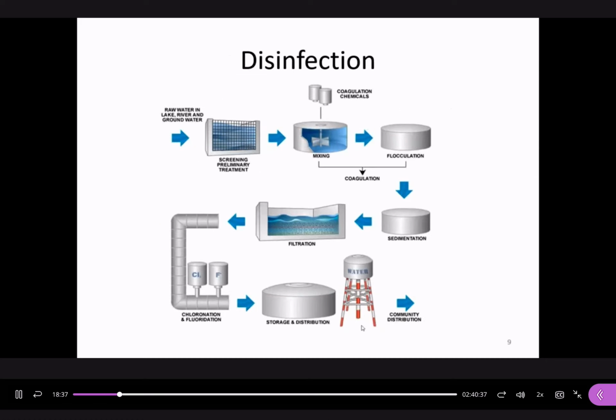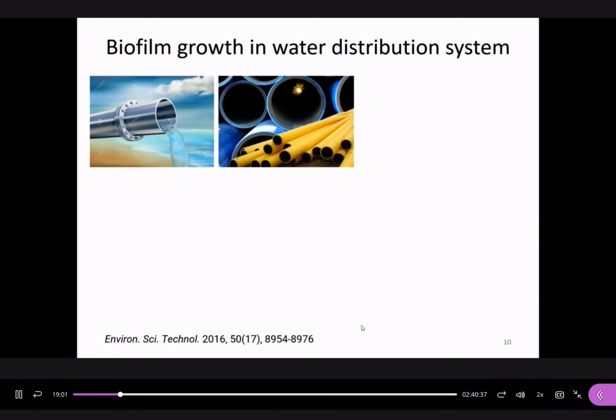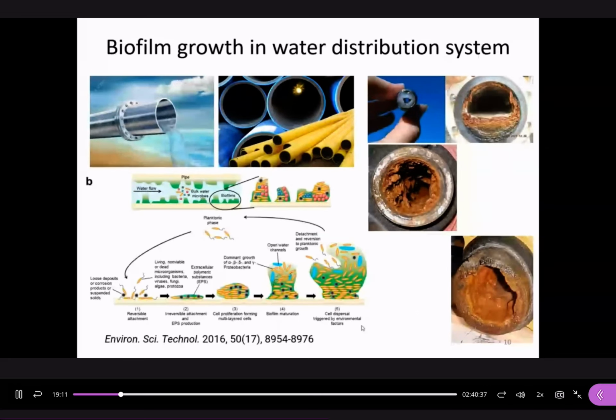Right. This is the treatment process train. I just want to refresh your memory again. Our process train: screening, coagulation, flocculation, sedimentation, sand filtration, and then disinfection, and storage, and then distribution. So each topic, one lecture. The biofilm is very nasty, as we discussed in membrane separation, right? Biofouling. Microorganisms grow in the pipes as well. Once they have grown on the surface, it becomes very difficult to remove. So we add a certain low concentration of disinfectant in water.